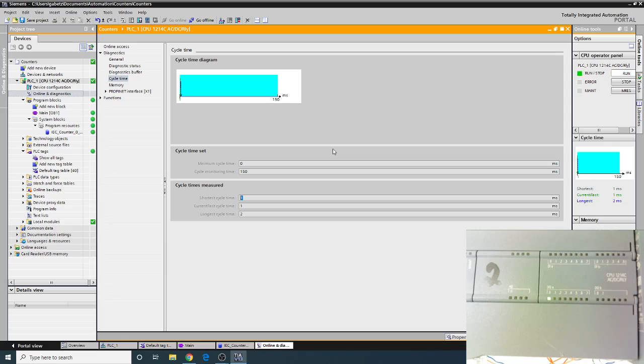Now, if we all of a sudden are at 2 milliseconds, we can only count 250 bottles per second. So you can see how our program going 1 millisecond bigger all of a sudden plummets how many bottles we can count. Now, how many programs are actually running at 1 millisecond?